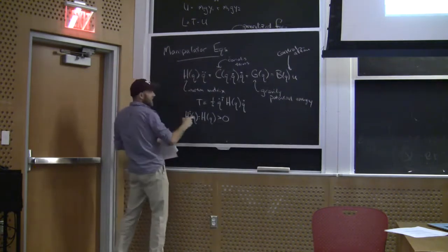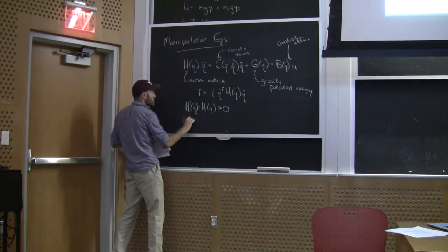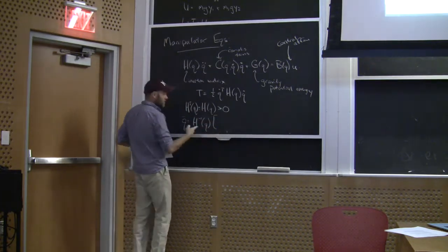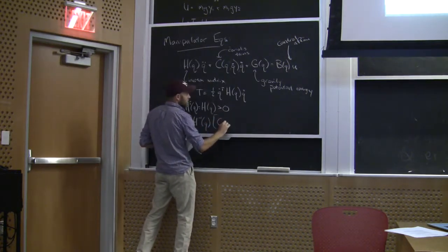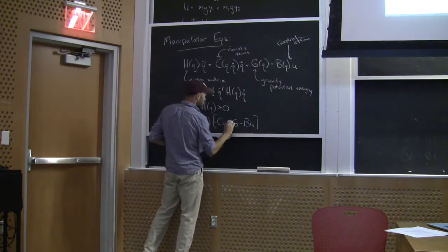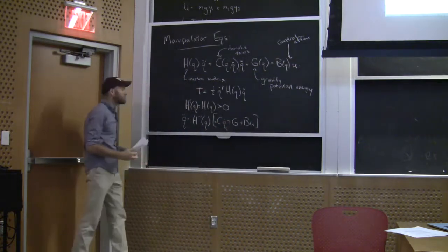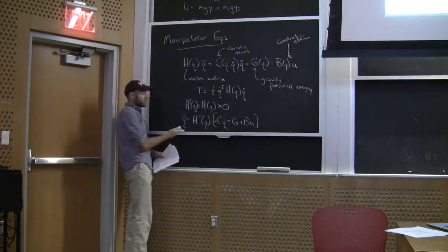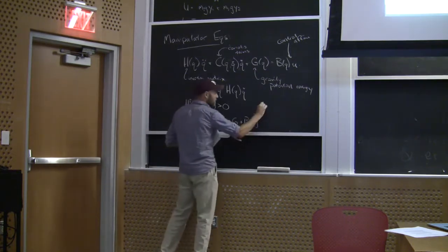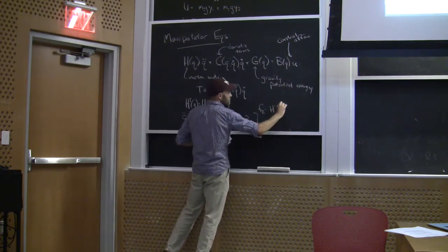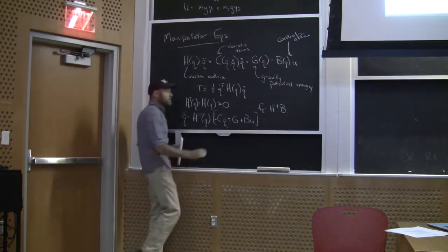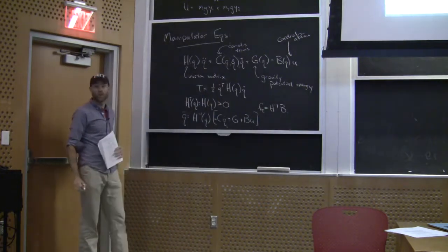Right? The fact that H is invertible, that it's a positive definite matrix, means I can always take its inverse, so I can write it back in the form that's more familiar to us, with a big complicated F. Got my signs wrong, something like that. I can write this as my nonlinear differential equation with just Q double dot on this side, and F1 is sort of all this stuff. F2 is H inverse B, right? Everybody square on that, yeah?